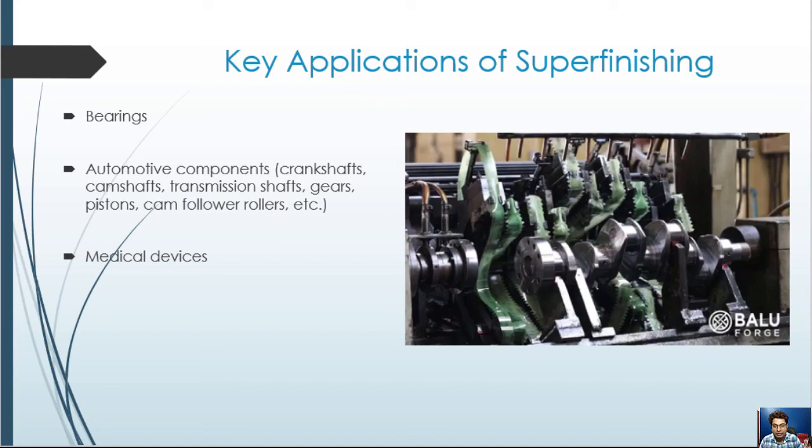The specific energy is in the range of 50 to 700 joule per cubic millimeter and is made up of cutting and sliding action. The specific energy due to cutting consists of chip formation and ploughing components. The ploughing component is dominant when the material removal rate is low. When the material removal rate is high, the ratio of ploughing component to chip formation component is smaller.